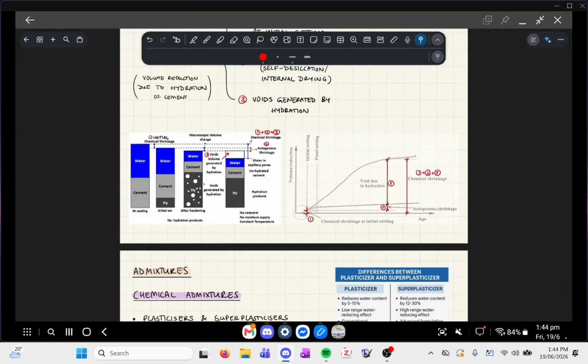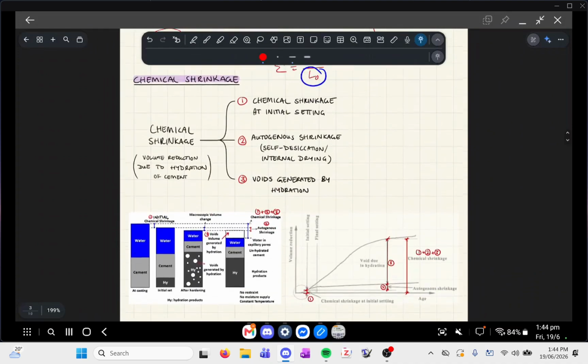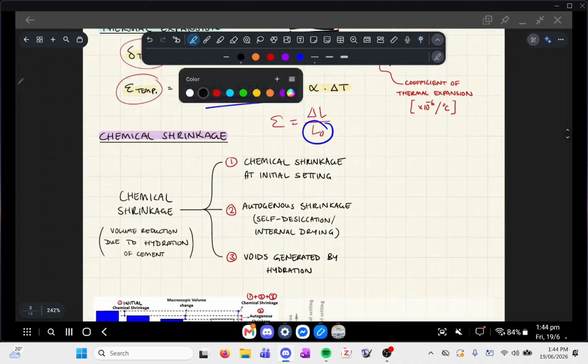Yes. So is the difference between drying shrinkage and chemical shrinkage? So drying loses water through just physically losing it through evaporation and through bleeding, and then chemical, it loses water from its chemical reaction, like it's being consumed.